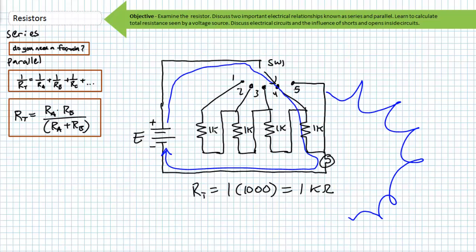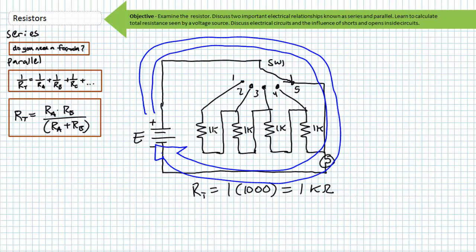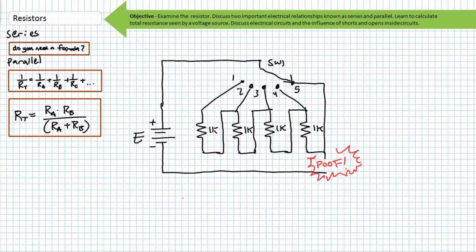Now again, assuming our light bulb has 0 ohms of resistance, an obvious fallacy, what would happen if we put a 5th position on our switch and changed our selector switch to this 5th position? In this case, there is no opposition. In this case, we get a tremendous surge of potentially damaging current until our light bulb filament simply melts, becoming an open, at which point all current flow ceases. The moral of the story is, always have resistance in a path.